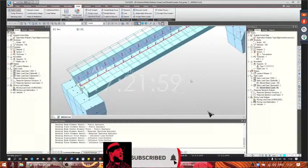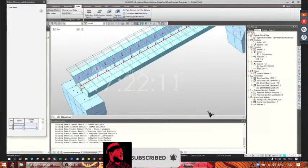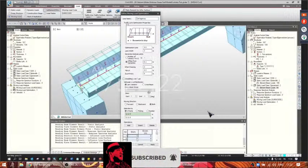As for the previous one, in this model we use the moving load optimization to simulate the traffic loads. Moving load optimization. We create a carriageway. In this case, since the model has no transversal element and just a single girder, we choose the vehicular load distribution as a lane element.